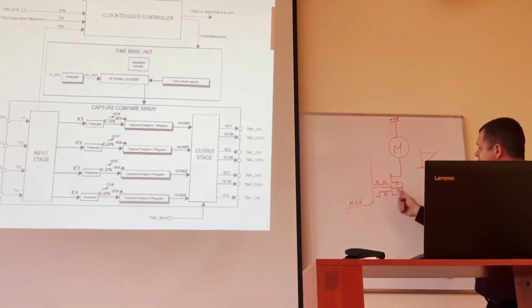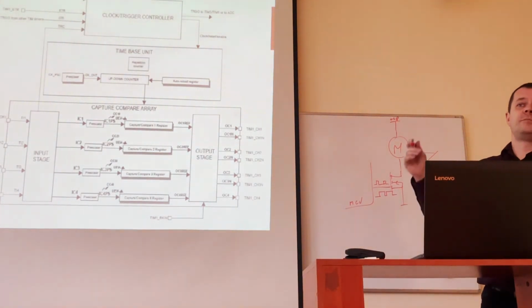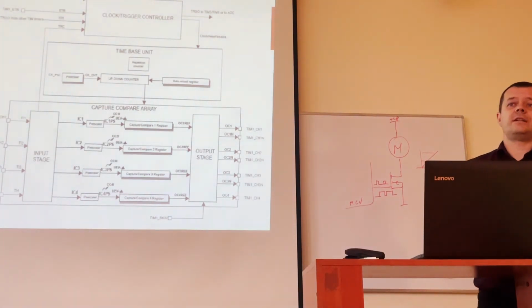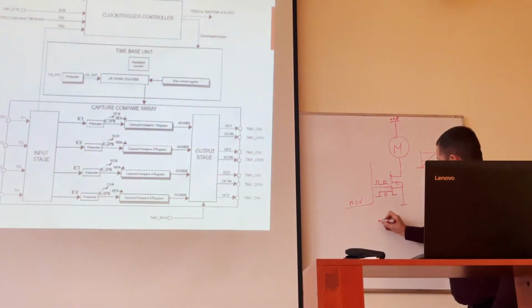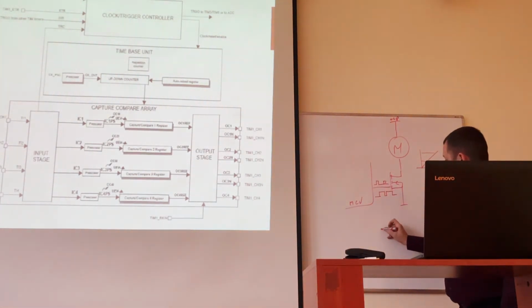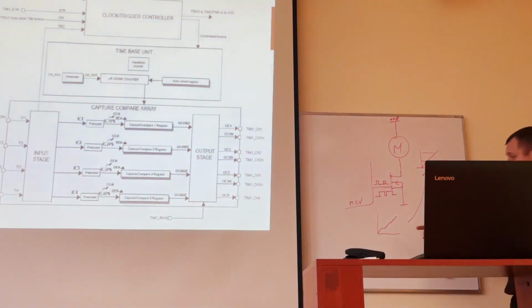Why don't we use the transistor in a linear fashion? Why do we use PWM modulation of the transistor and not linear operation? Theoretically we could put some voltage here, use the DAC converter and put a certain voltage at the input, drive this voltage, and get this characteristic at the output. Why don't we use the transistor in the active mode?